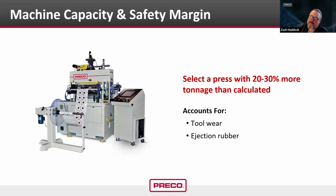So I'm relying on that extra 20% to make up for that. If I am doing the brass tacks calculation, we're getting down to it. The reason I still want to leave that 80% utilization of my tonnage, that 20% safety margin out there, is because I need to account for tool wear, and then I need to also account for some ejection rubber.